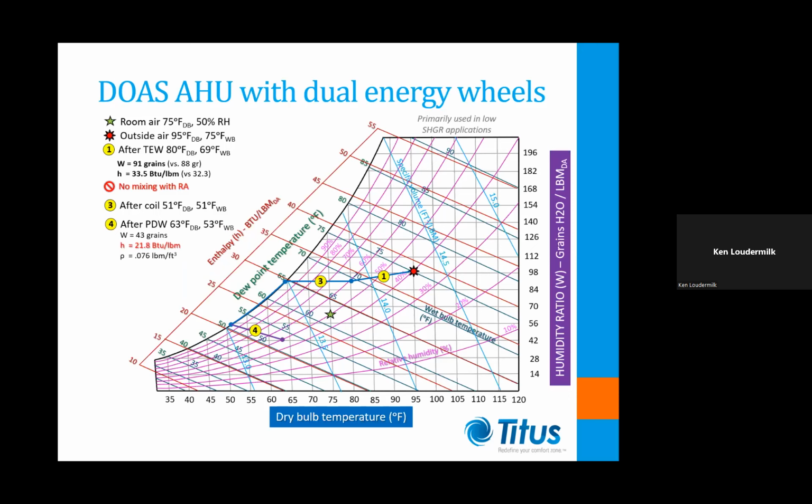In turn, heat transfer from the return air raises the dry bulb temperature of the conditioned air while lowering its relative humidity to a level comparable to that of the return air entering the wheel. The process line that results is largely parallel to the enthalpy lines on the chart, although there is a slight increase in the leaving air enthalpy since the process is not 100% efficient.